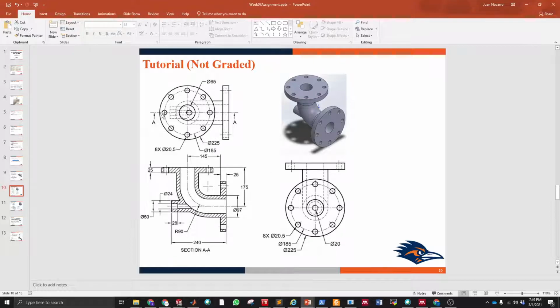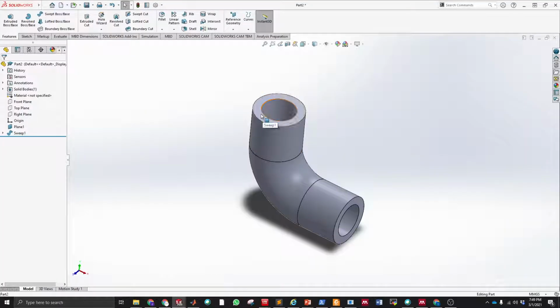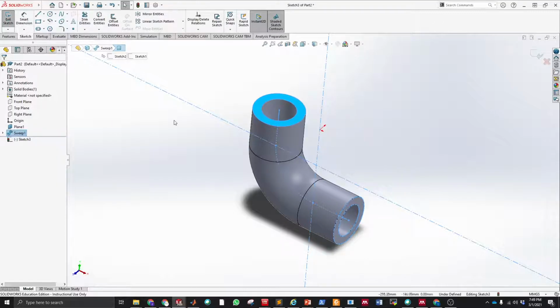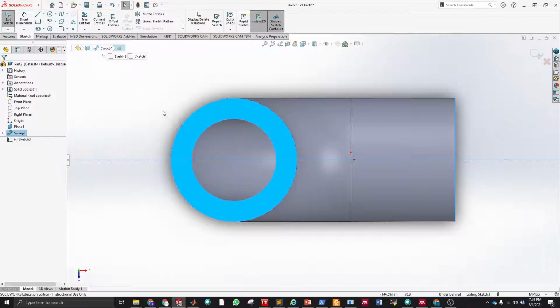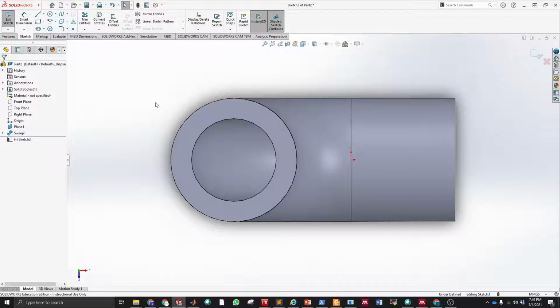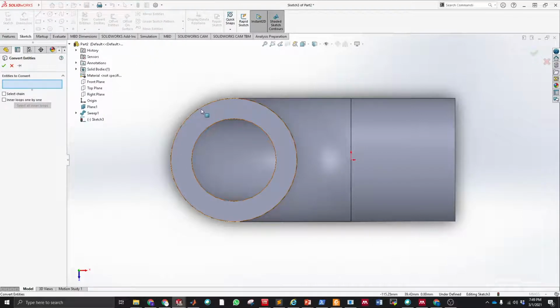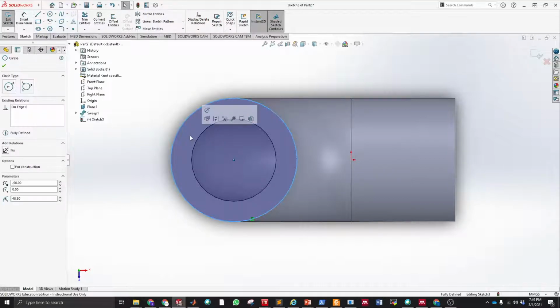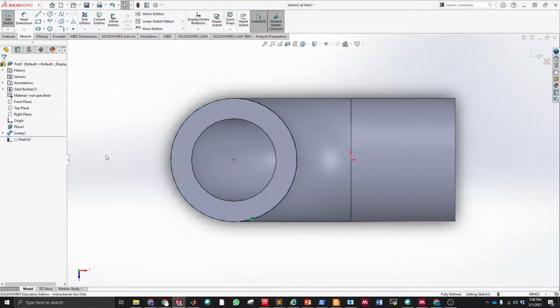And then we can create these attachments on the top and on the right. So first one, the one in the top, I just go and select sketch in that face, Control 8. I can select the convert entities here to create these two circles, or at least this circle. This one is actually going to be for construction because all I want from that circle is the center.